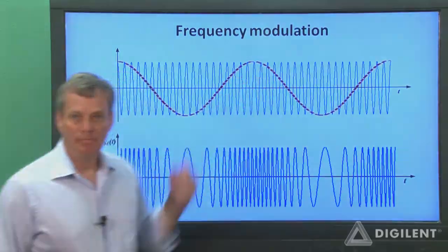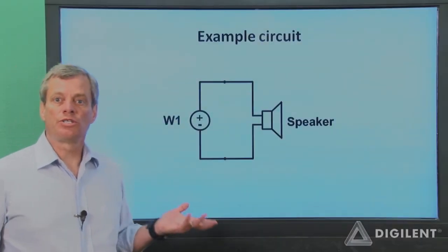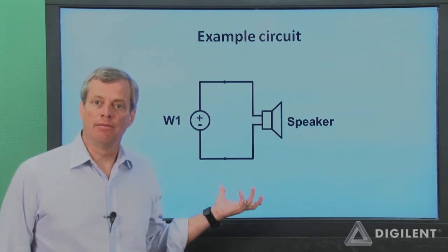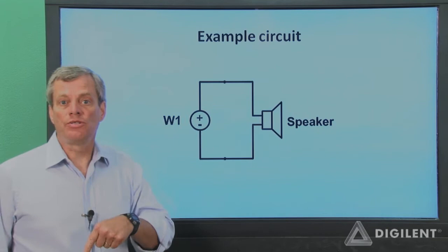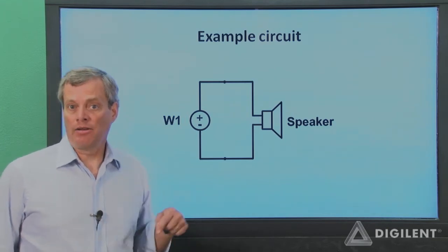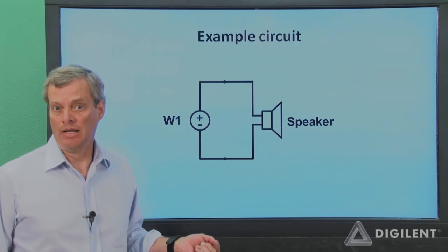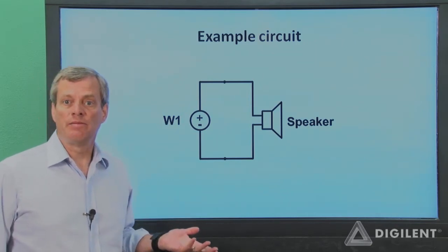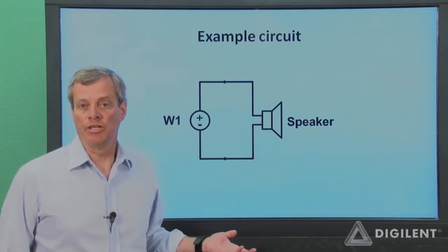We're going to use a speaker to listen to our frequency modulated signals, so our circuit is the same as the second AWG project, the one on sinusoidal sweeps. Again, I'll use a set of speakers plugged into the Analog Discovery headphone jack so that the audio quality of the video is better. Since the circuit creation is the same as the last project, we'll just skip ahead to creating FM signals with the waveform generator.